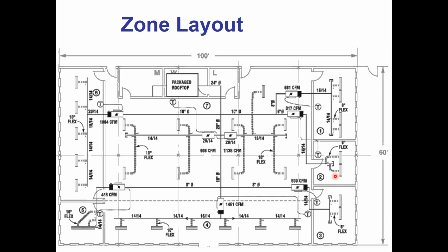They'll be upset forever. The interior zone could have been one large zone, but on this job they decided to split it in 2. Maybe it was just easier from a ducting standpoint. But we can have those guys be synced up so they have the same set points all the time, so they don't fight each other in that large open area. These 2 guys on the inside, you see they don't have little black boxes on them, but all the perimeter ones do. So all these perimeter zones on this project were designed with either electric reheat or hydronic hot water heat. All the perimeter zones on your building are going to need some kind of supplemental heat. The interior zones are not going to need that. That's going to be one of the major differences here.